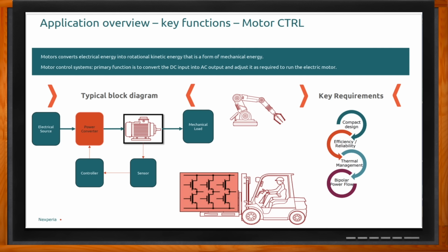So on efficiency and reliability, the smaller the components are, and the fewer of them you use, the mean time between failures, MTBF, will be increased because you have a lot fewer devices that will fail over a period of time. So that's always a good thing from the mechanical engineering perspective. We never forget those guys. We work with them hand in hand. If they need that motor to operate 10 years without anything broken, most of the time it will be electronics that will fail. But with the GaN approach, the higher frequency, size reduction, and component reduction give it a much better feeling for the mechanical guys that actually have to control the shaft going to the load.